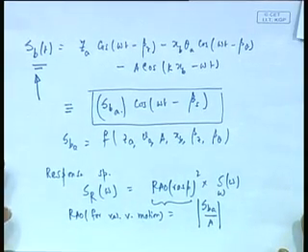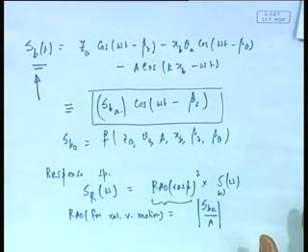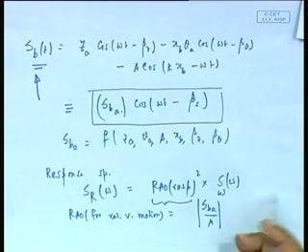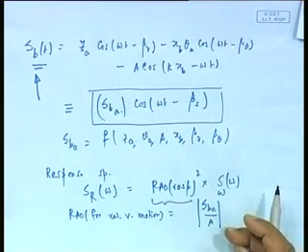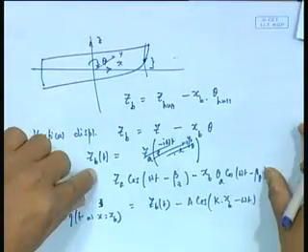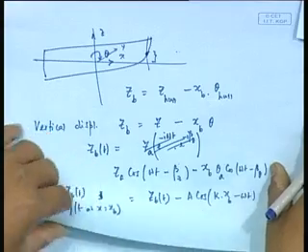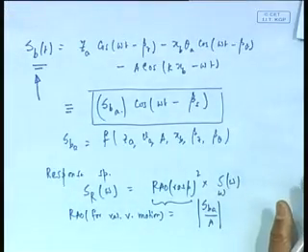The point I am making here is that all derived responses are also responses, and I can always determine the spectrum for those responses simply by taking the amplitude of that response divided by A as the RAO, that is all. If I were to, for example, find the vertical motion spectrum, then I would take Z_BA, find the amplitude of this quantity and take that as the response spectrum. So this part is the straightforward part.